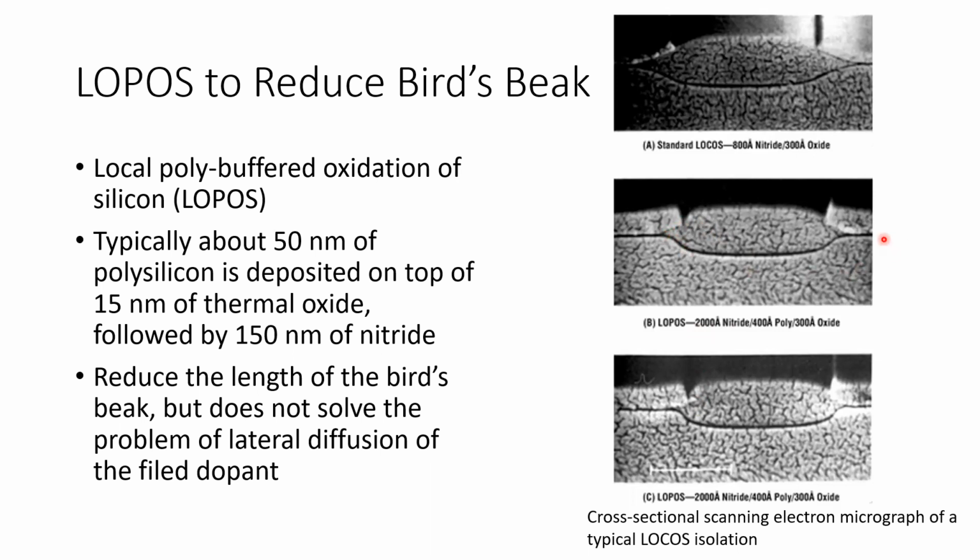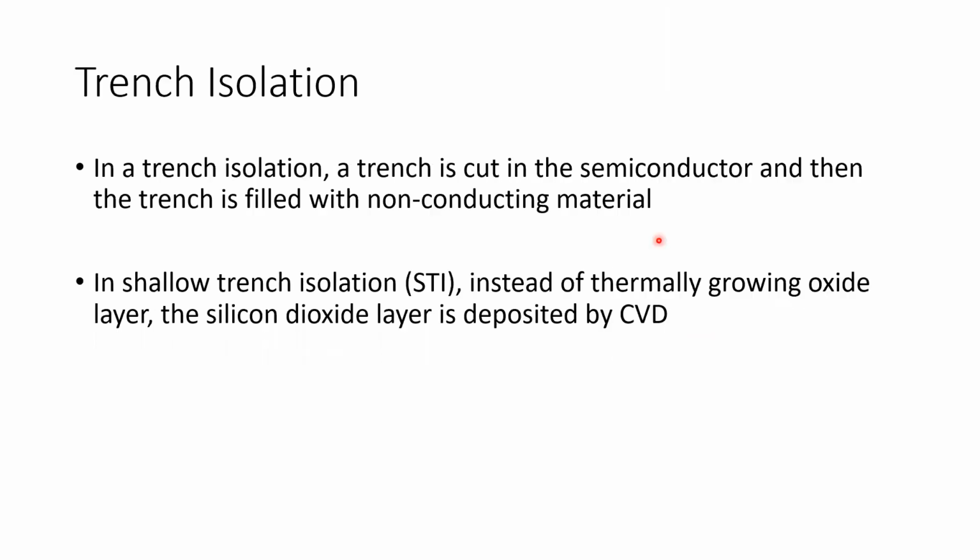This reduces the length of the bird's beak, but it still does not solve the problem of lateral diffusion of field dopant. The diffusion still happens because this is still a thermal process, 1000 degrees C. So we use another method.